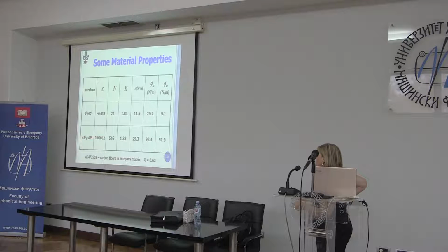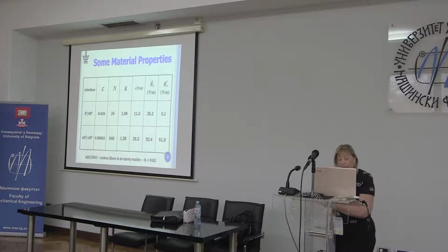In the plus 45, minus 45 degree problem, we did do three-dimensional analyses. We had 26 specimens, and we had 21 values of K along the delamination front. So we have 546 values, and you can see how this parameter K is influenced by the number of samples. So it went way down. You still paid a price, but not the same magnitude of a price of getting a 10% probability.